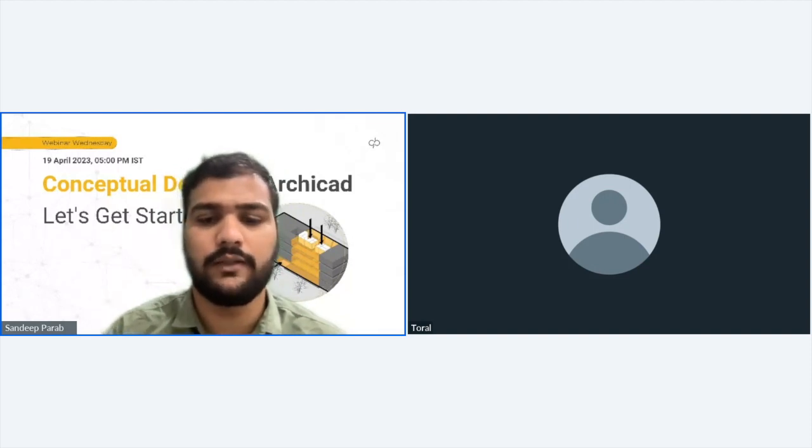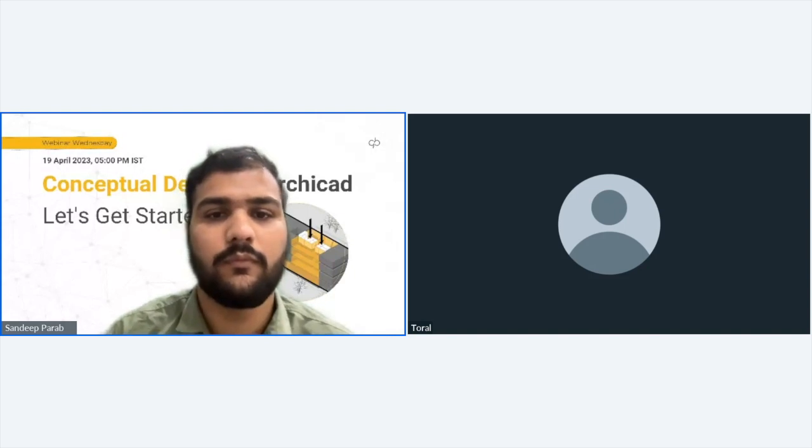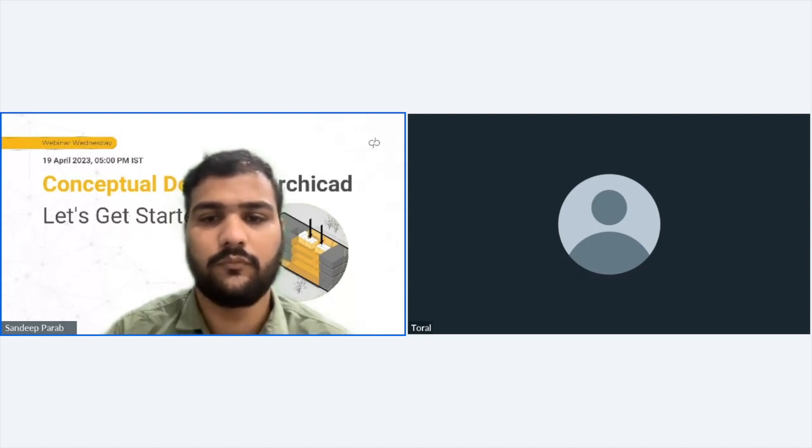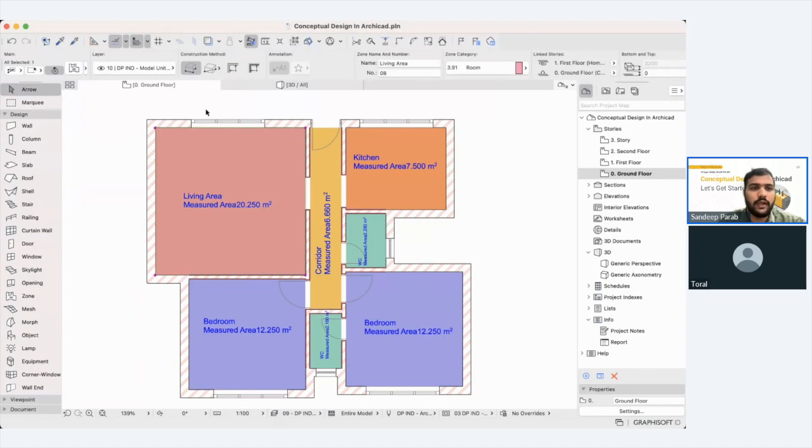of glass. So if you can see, I will just share my screen once again to show you the same. Okay, so I guess my screen is visible now. So if I click any of the zone and I go to the zone settings, here I have specially made a surface for the zone.